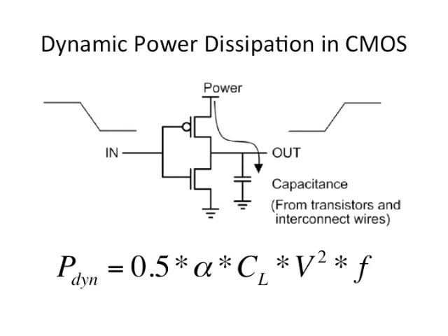What happens before the setup time? Are there a lot of transitions? All that doesn't matter as far as the functional correctness of the system goes. You just have to ensure that the final value of the logic net stabilizes at least a setup time before it gets captured by the clock. But of course it's not desirable to have a lot of these transitions because you are unnecessarily wasting power. So this is basically dynamic power dissipation.